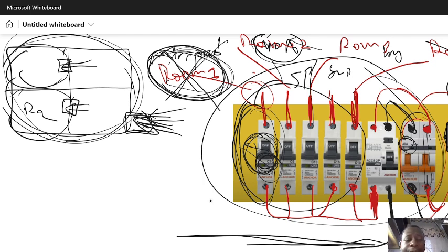That's why, for example, if we are in this level, we have different rooms, but this one is off, shutting down this block. The other is working. It's not a problem, because now we know directly that the circuit breaker has tripped off. Why? Because here we exceeded the limit, so we have to remove the load and switch on the circuit breaker again. We must remove the load, because if we do not, something will happen again. So we have to be careful about our load.